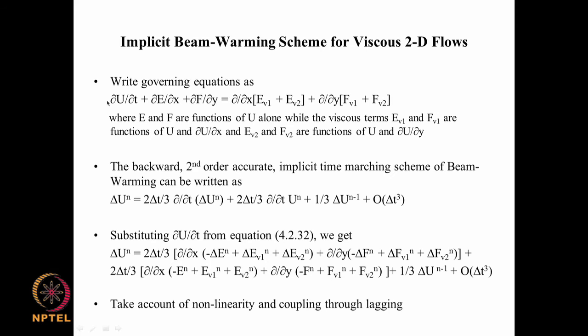So, we write the governing equations as ∂u/∂t plus ∂E/∂x plus ∂F/∂y, the temporal term and the advection term, equal to ∂/∂x of the viscous terms. E and F here are functions of u alone, and we have seen that ∂E/∂u is A and ∂F/∂u is B.